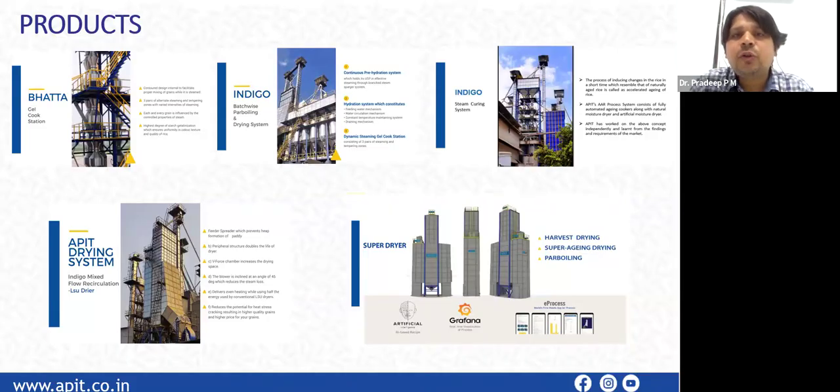For example, if we are doing steaming, super aging or parboiling, the moisture will be high after the process. So once again, we have to reduce this moisture to the safer limit of 12% before storage or before milling. This can be accomplished in a batch-wise or continuous process on a large scale, that means around 50 tons per batch or 60 tons per batch, or 10 tons per hour. At that scale, we have to do it to balance with the production.